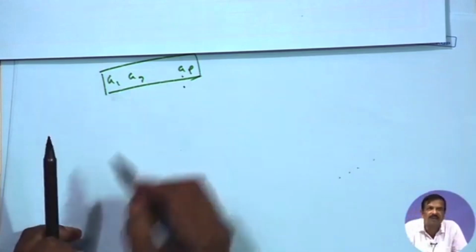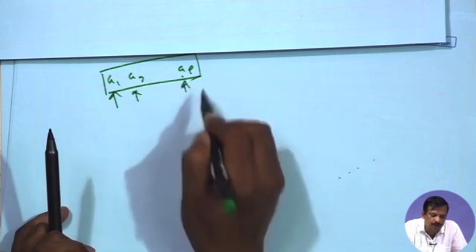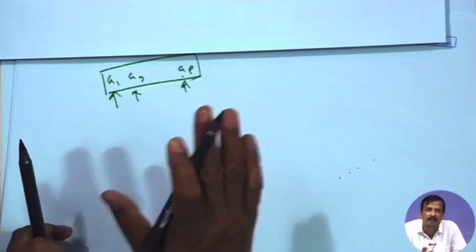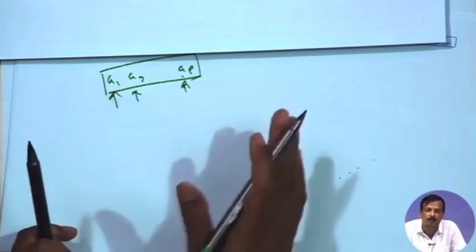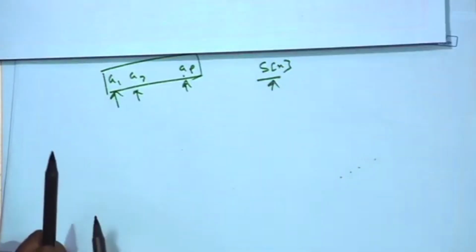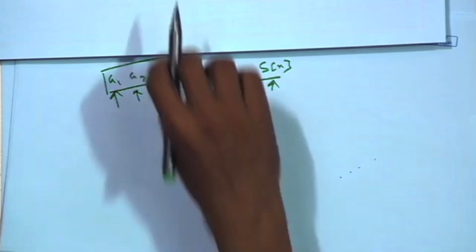So, this is nothing but a filter, and those are the coefficients of the filter. If I design an all-pole filter using these coefficients and pass the previous p number of samples, then the present speech signal can be predicted. This is called linear prediction.